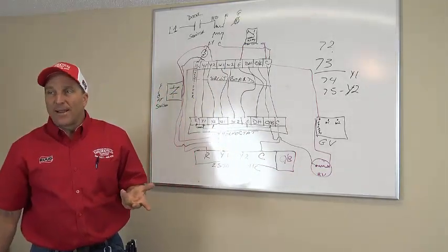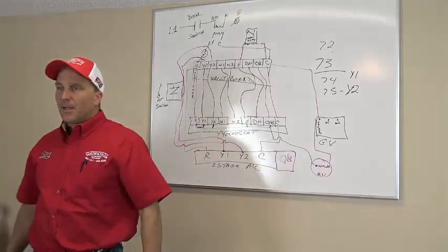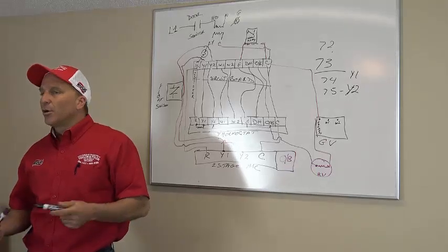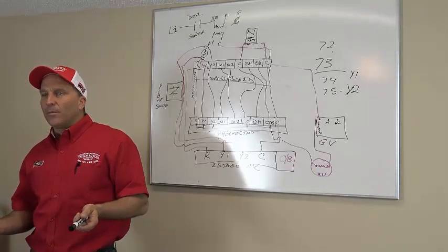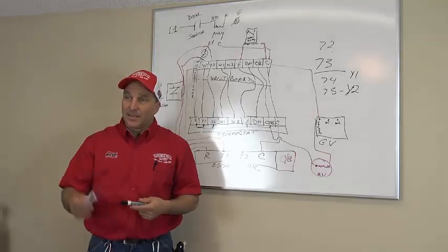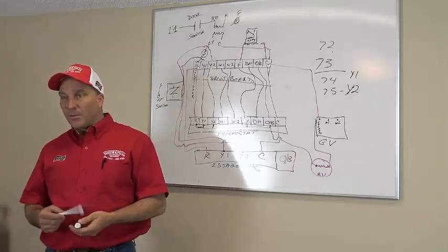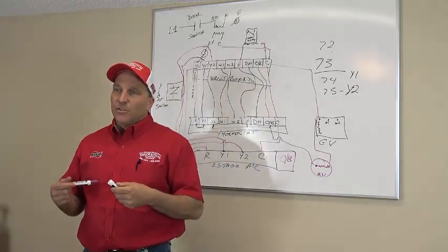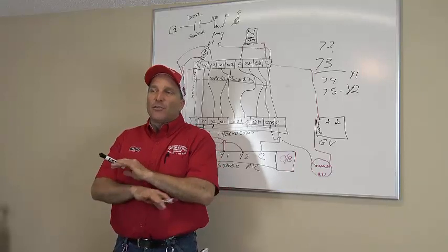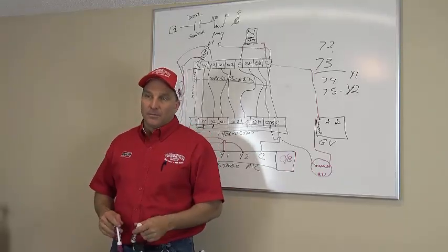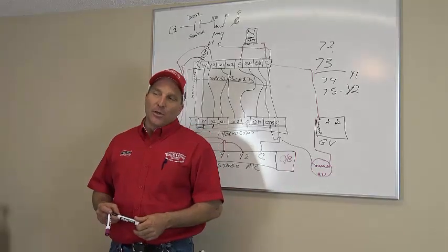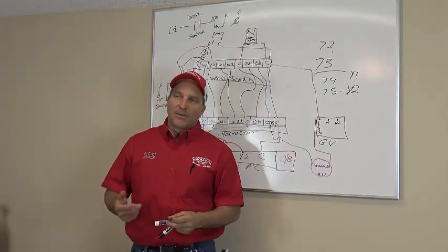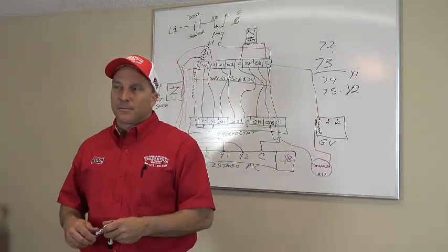So let's just say my heat pump broke, and I need emergency heat. Every heat pump has got to have emergency heat. Could be emergency heat strips, or it could be emergency dual fuel gas heat, propane heat. Okay? Could be any kind of heat. Alright? I have a geothermal system. A geothermal system is a heat pump, and I have no backup heat. None. Now, how can I have a geothermal system, and I just got finished telling you all systems got to have a backup heat, right? And I just got finished telling you I don't have a backup heat. No heat strips in my system.